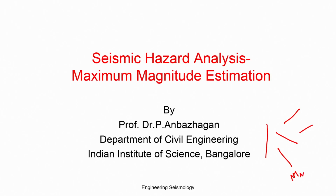By doing this entire process, you will know what seismic sources are active in the region, and what the M minimum is. M minimum means the minimum magnitude that occurred in the region, and the complete period.